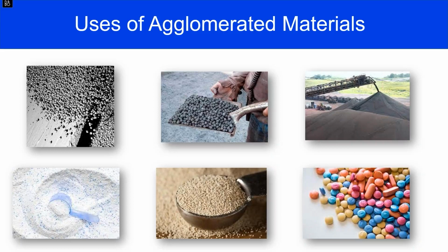The process for agglomerating, you can see on the left side of the screen, it's a drum granulation process where you take the wet cake that comes out of the wet ball milling and filtration process into a tumbling drum, and you actually come out with these particles out the end. They fire them, and the picture on the right is the amount of iron ore pellets they produce. They actually produce 1,000 tons, 2 million pounds of iron ore pellets an hour. Yes, actually an hour. It's an incredible amount of material. So this is one of these big volume agglomeration processes.